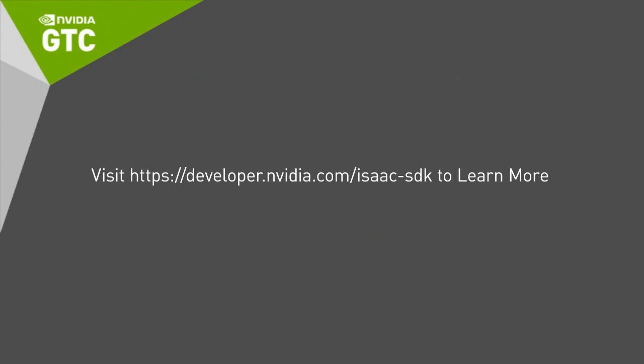And of course, you can also run on AWS, which has the Tesla T4 cards. When you run with AWS, of course, you need to pay for the AWS service. But the PhysX Sim container can be run locally on your Ubuntu machine. Another question people ask is what kind of robots can be simulated. As Hamad said, if you have a URDF file, you can try to import it. PhysX Sim will try to parse that and import the robot for you. Of course, URDF might come with certain values that might not be correct or are missing.